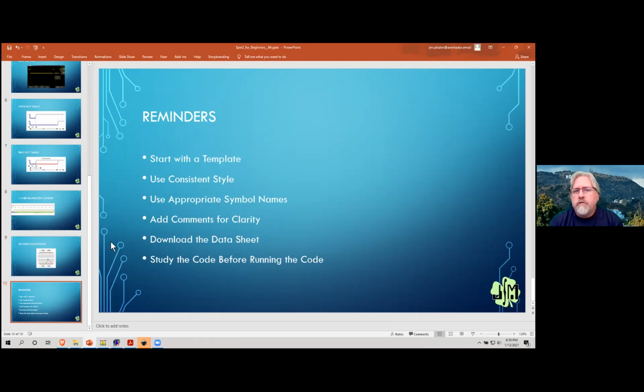So we'll talk about those things too, especially as we get into those topologies. So asynchronous serial, like we're talking to a terminal, we can do that in code, or we can do it with a smart pin. Synchronous serial, SPI, we can also do that in code or a smart pin. So we'll show different ways to do it. Just as I showed today, we could write one-wire code in Spin, but it's a little bit more efficient to do it in assembly. Again, the goal is to show you a couple of different attacks on the same subject so that it sinks in, because we all have to hear things differently and sometimes multiple times.